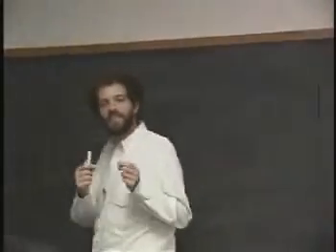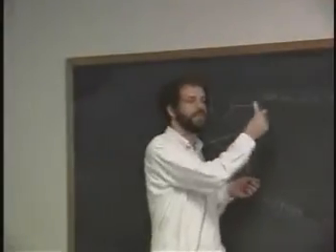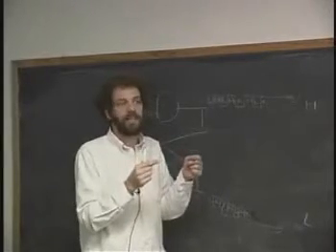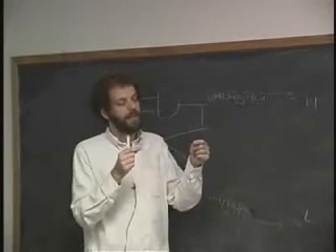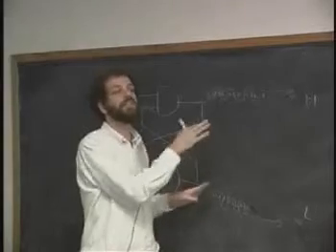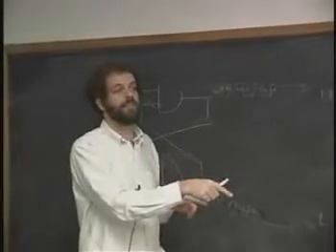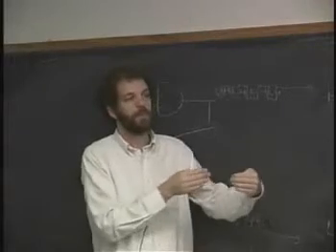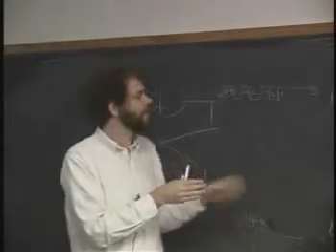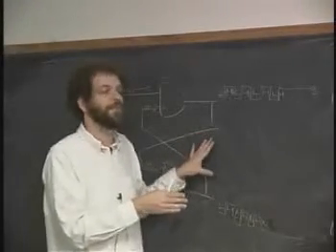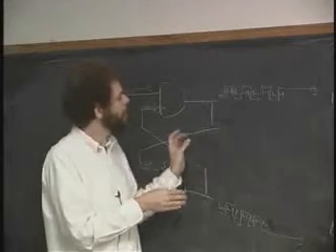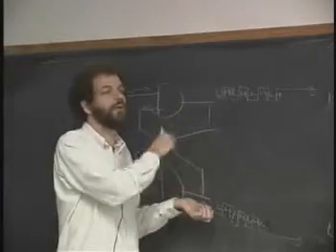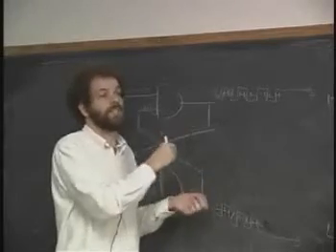That gives you an idea of how the ones might win out over the zeros or the zeros over the ones. Of course, it's not a way of guaranteeing that we'll get out. We may be stuck there forever. It all has to do with the exact time that we hit each other, exactly where we were with respect to each other. And it is theoretically possible for a circuit like this to oscillate forever if we happen to start it in just the state where it's balanced between going one way and going the other way in a dynamic sense.